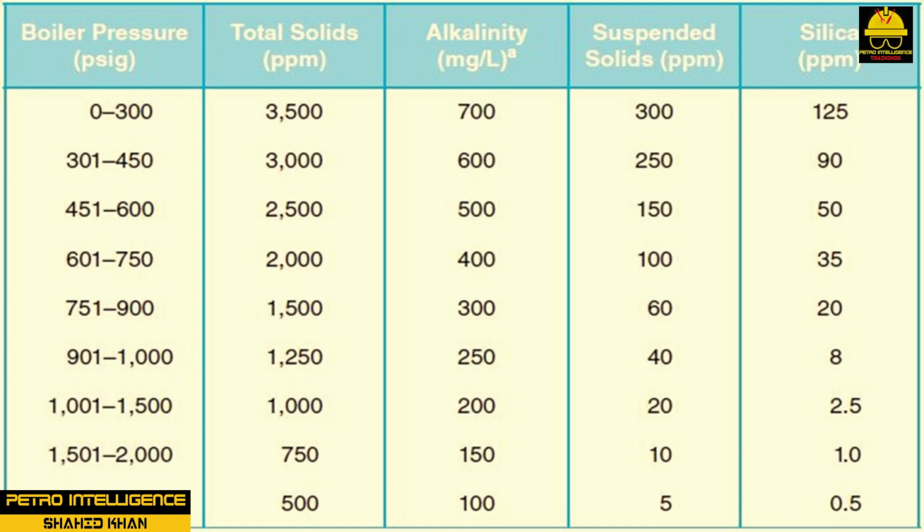Examples of dissolved solids are sodium chloride, common table salt, calcium carbonate, limestone, silica, sand, calcium sulfate, gypsum, magnesium sulfate, Epsom salts, magnesium carbonate, dolomite, hydrated sodium sulfate, Glauber's salt, aluminum, iron, manganese, fluorides, and other trace substances. Impurities must be removed from water before it can be used in industrial applications. This table shows the standard for boiler operation established by the American Boiler Manufacturers Association, ABMA.